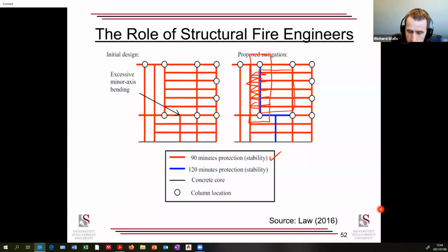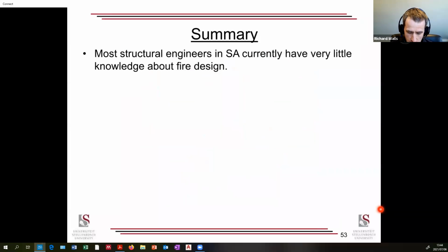It's a critical member, with high lateral loads on the minor axis. So we increase its resistance. We give it a little bit more capacity. Same thing, this beam expanding may push on that one, and these ones that say are critical. So we may find that strengthening key elements reduces the chance of failure. Same thing, having a careful look at your columns and your beam-column connections, and putting in connections that can accommodate heavy movement, all makes a major difference to this sort of testing.